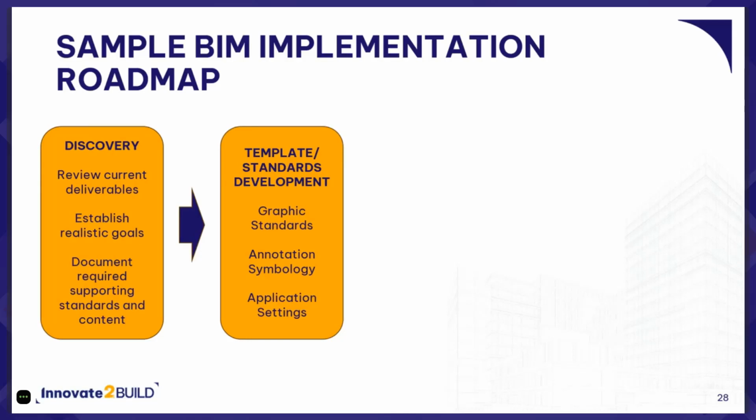I know people that have used AutoCAD for years without a really defined AutoCAD DWT file template, right? They just use it with the default settings, or they'll bring up a drawing that they did a year ago and save it as a new drawing and start from there, right? You can't do that with technology like Revit. You've got to have a template to start with, and that template really needs to store all of your firm's custom standards and content.